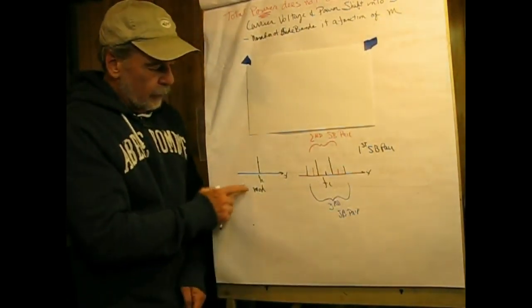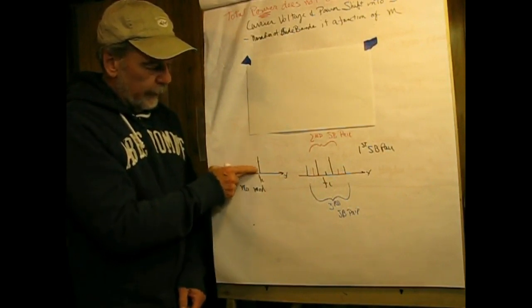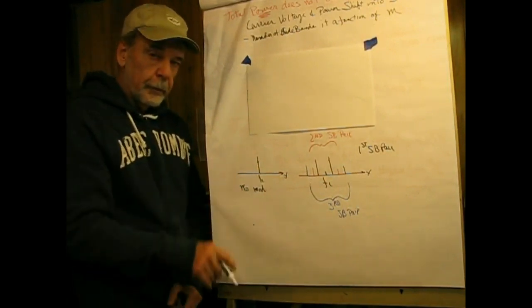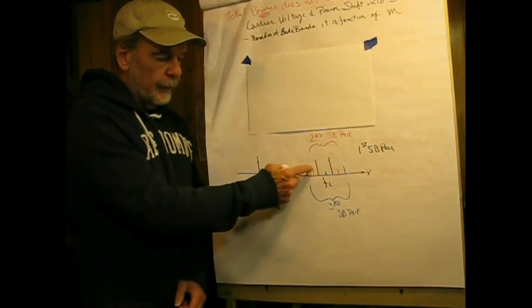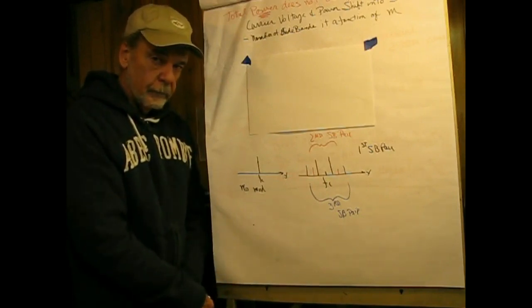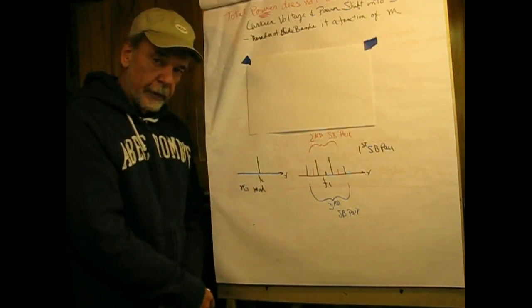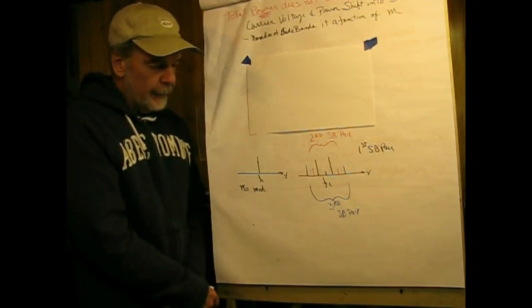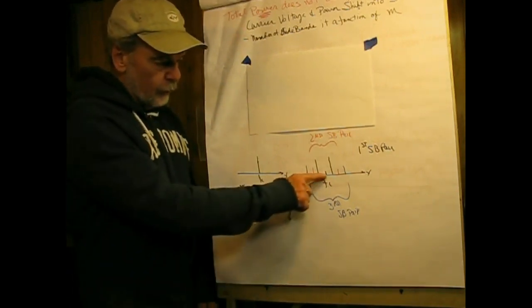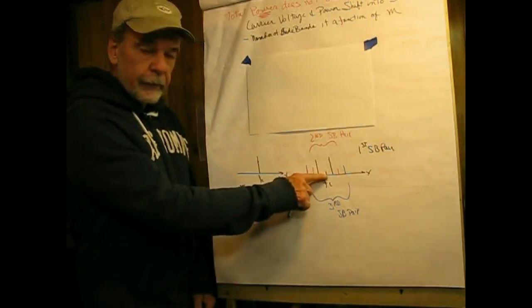There we go. So an unmodulated carrier would look like a single spectral spike, and always remember that spectral spikes are sinusoids. There's no triangle waves or square waves in a spectral spike. It's a sine wave. And then if we apply modulation, what we see is that the carrier dropped.